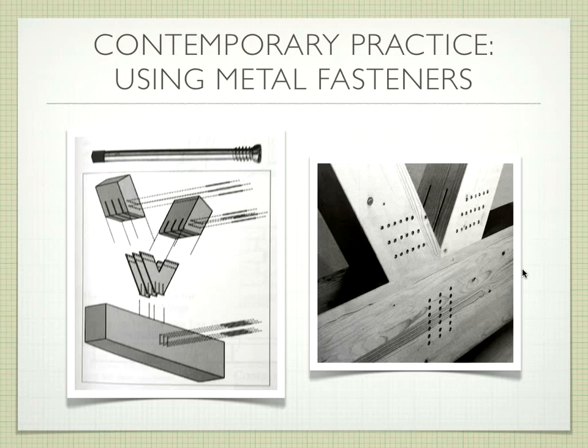All those screws are sunken into the wood? Right, they'll be countersunk into the wood. Theoretically, you could putty them all so you wouldn't see them. So this is a way of hiding the steel involved in connecting these, but it's still there. Very commonly, with connections like this, anytime there's a beam, they'll have fins inside that you can't normally see. Even if you're bolting through, you have another piece of metal helping hold the whole thing together. So this kind of hidden steel plate is very, very common.